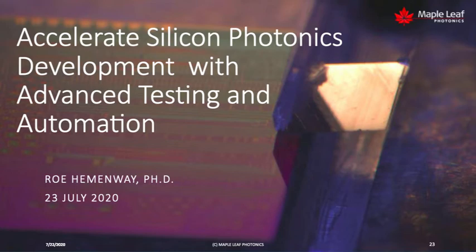It's really been a delight to be working with Luna on this activity because their machines are really astounding in terms of what they provide in terms of insight to the chips. And what I'd like to talk about regarding the optical probe stations is how do you attach these wonderful high-resolution instruments to your chip when your chip is either in a wafer form or a die or even on a submount or on an eval board. How can you set it up to probe your device and even configure your device and even calibrate it or tune it up as part of the characterization?